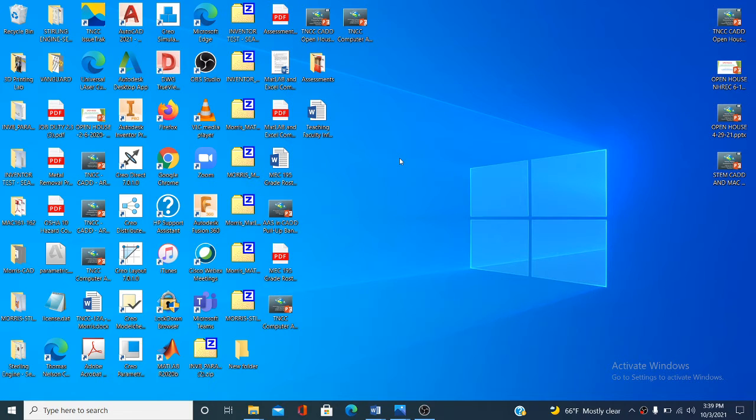Basically, what we're going to do is create a model and dimension it, and we're going to write formulas for the dimensions. In other words, if you change one dimension, it's going to automatically change all the other dimensions as well because it's all relative. And it's also going to update the drawing to reflect your dimensional changes. So let's go ahead and open up Autodesk Inventor Professional.